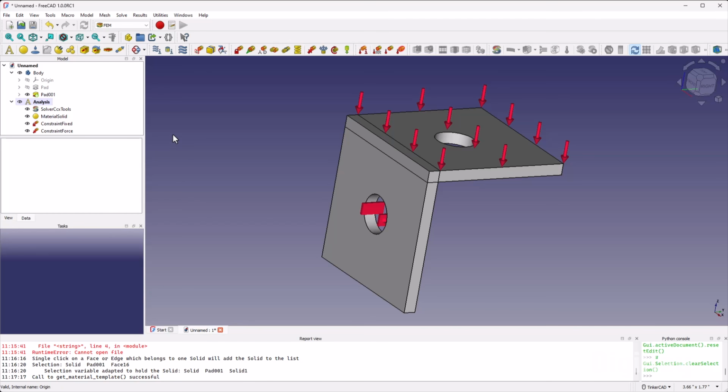Next, we need to create a mesh. This is used for the actual calculations for the finite elements. It basically breaks down our solid into finite elements, like little triangles, and uses those points or faces to calculate numerically the forces acting on this object. It could be temperature, it could be a temperature gradient, it could be looking at deflection, how much stress, but that's where the idea of finite element analysis comes into play.